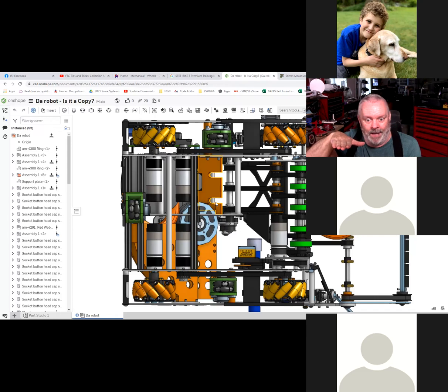Right, and you need high maneuverability. The downside to these wheels is that, just like the Omni wheels, they don't hold position terribly well if somebody pushes on you. They're not bad, but if you had just fixed wheels and somebody pushed you from the side, it's super hard to get you to move. With these, even if the wheels are all locked up, you can actually get all of those wheels to move. So there are some of the trade-offs.